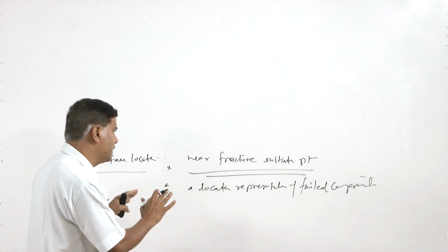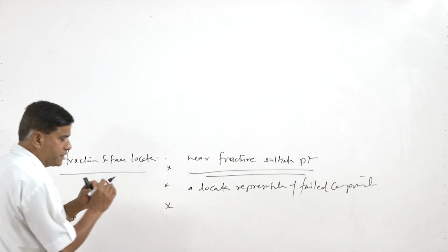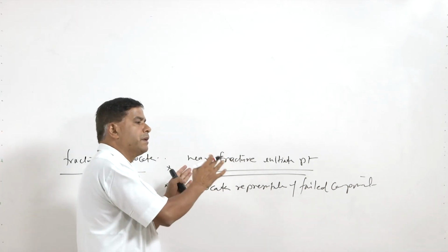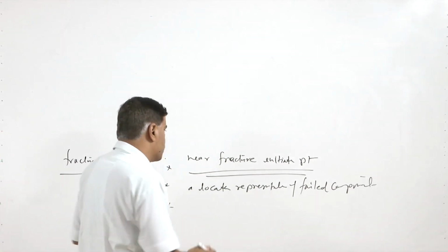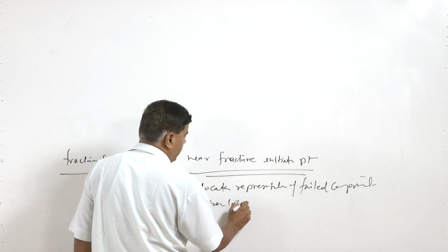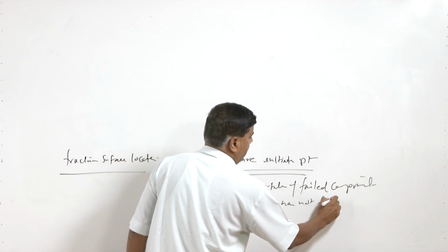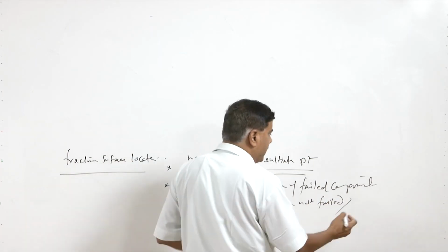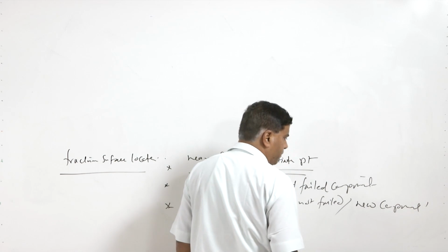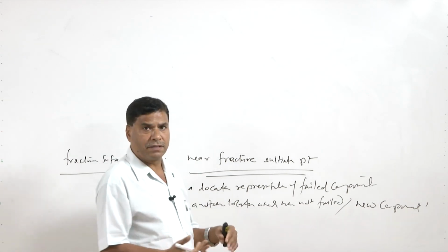So, this is another thing which is kept in mind while selecting the sample, and if the component has failed from a particular point, to identify if in that zone only there was some problem or other areas were good, we also try to collect the sample from another location which has not failed. Or we can take another new component for the comparison purpose, or another unfailed component which has experienced a similar kind of service conditions.